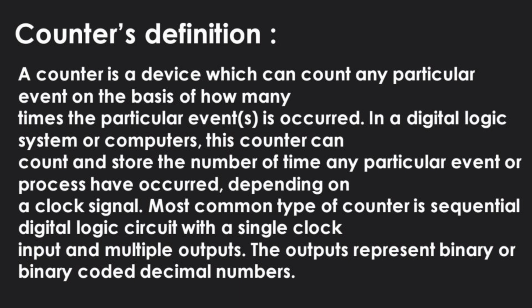A counter is a device which can count any particular event on the basis of how many times the particular event has occurred. In a digital logic system or computers, these counters can count and store the number of times any particular event or process has occurred, depending on a clock signal. The most common type of counter is a sequential digital logic circuit with a single clock input and multiple outputs. The outputs represent binary or binary coded decimal numbers.